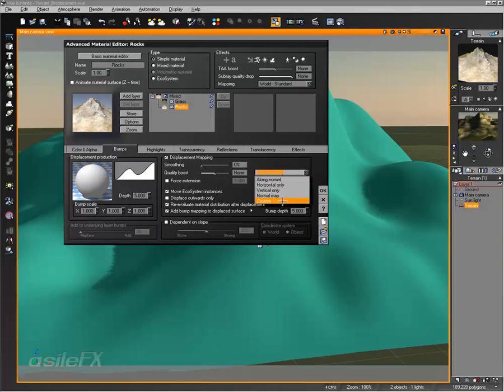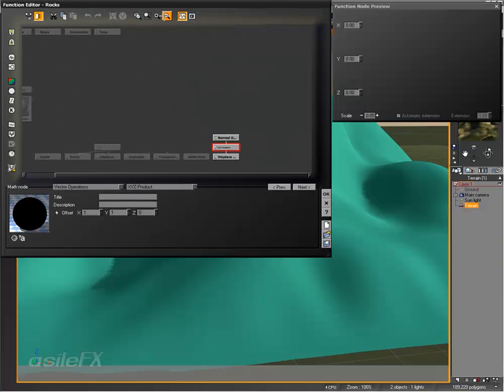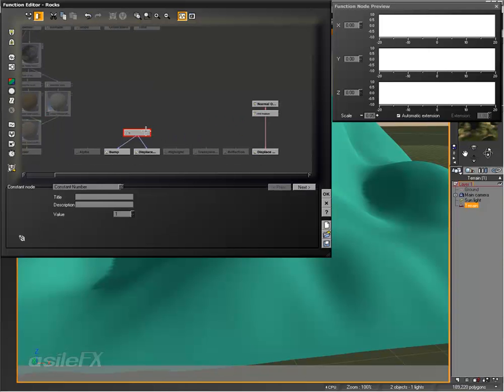If we switch this over to custom, we can now define anything we want and connect this to any vector whatsoever. So one thing I suggest is if you're having problems with some tearing, because you're completely limiting an axis, you can reduce one of the amounts rather than completely removing it. So if we wanted horizontal only, we could use 1, 1, and then on the z, instead of using 0, we could use a value of 0.1. So it's a very minimal displacement, but there's still a little bit there in case you run into tears.